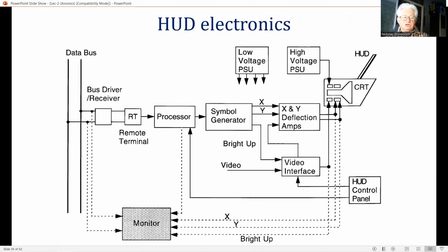The HUD incorporates electronics which monitor performance, both forward and reverse paths, such that the integrity of the system, defined in terms of displaying hazardously misleading information to the pilot, equals that of conventional head-down displays at a value of 10 to the power minus 9.